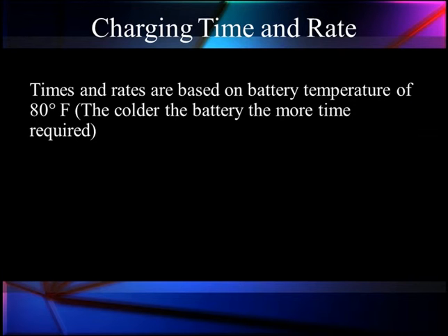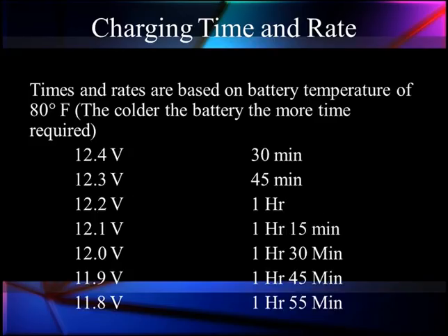Now, there is a specific time it takes to recharge a battery. We use 80 degrees Fahrenheit as a typical number. If the battery is colder than 80, you need to allow more time. Let me say that one more time. If the battery is less than 80 degrees Fahrenheit, it's going to take more time. One of the biggest mistakes people make about discharged batteries is they charge it for 15 to 20 minutes and say, well, that should get you down the road. But look at what it really takes.